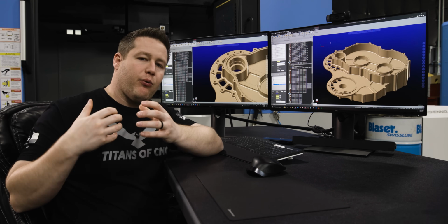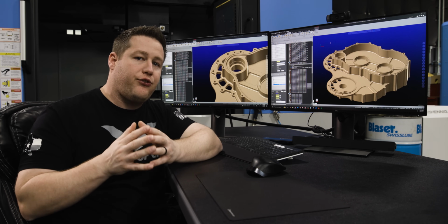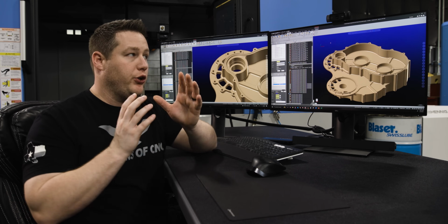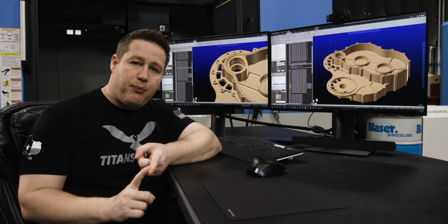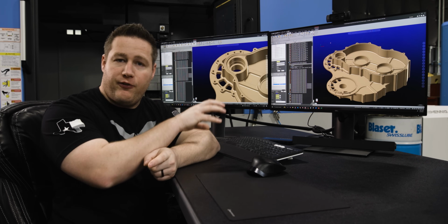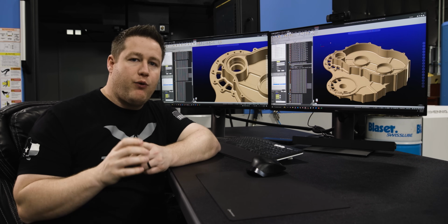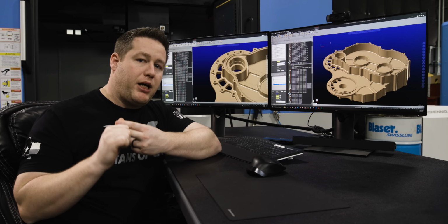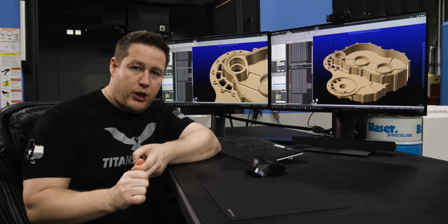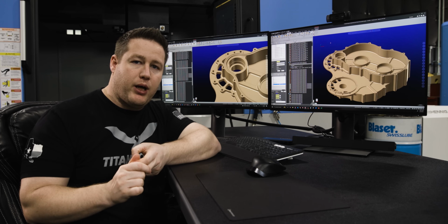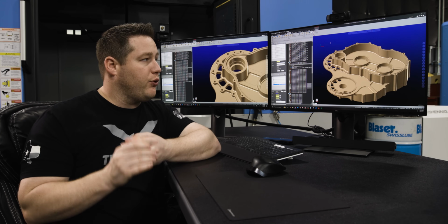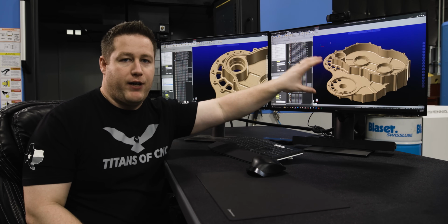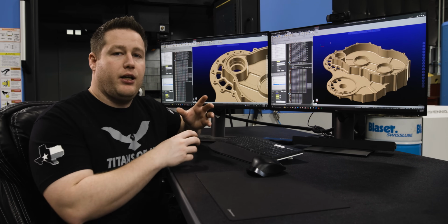Now guys, I know I threw a lot at you today, and I really want to make sure that you understand these three main principles when you're using CAM Assist. That is setting up your file correctly, that is bringing your fixtures in, setting your collision avoidance, all of that. Two, you want to make sure that your tool database is robust and you set up your cutting parameters the way you like. And three, give CAM Assist a very good model. Now you do that and I guarantee that you will get very good results out of CAM Assist.